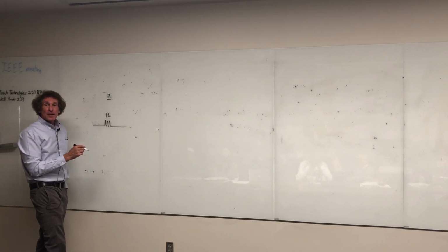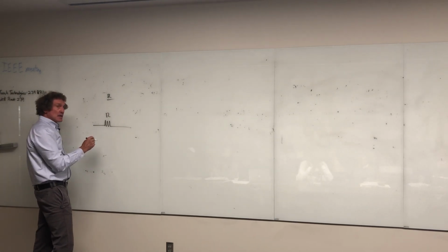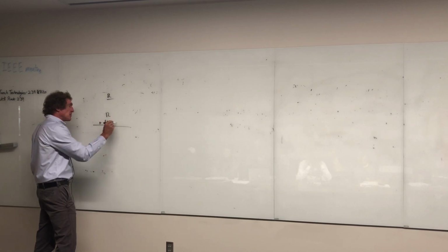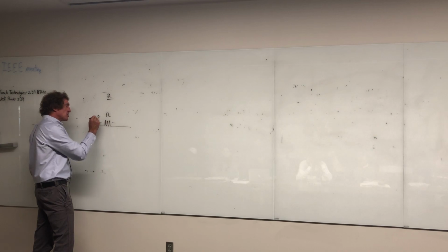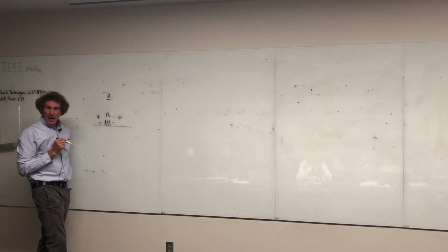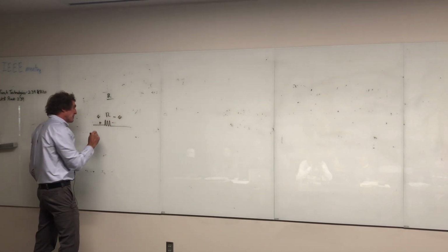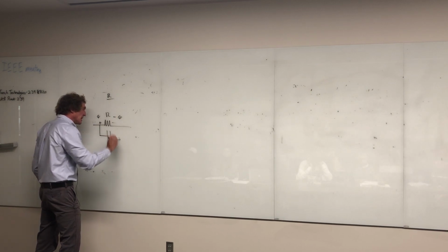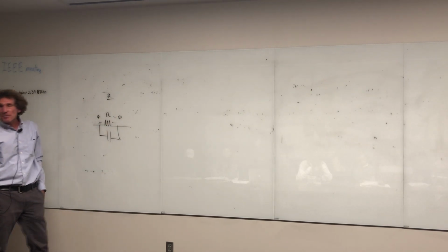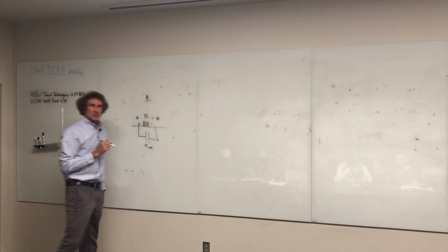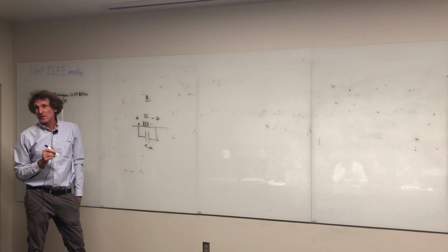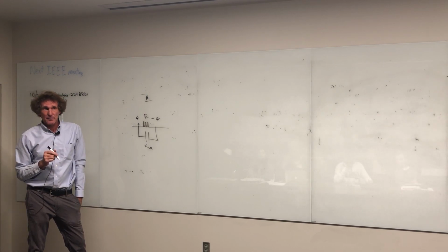In the real world, here's what happens. Because on a resistor, you develop a voltage difference with current flow. You also develop a charge difference, all right? That means there's a real effective capacitance. You can't get around this. There's some capacitance associated with that. You can call it CX the way he does. The X means unwanted. You would like to get rid of it, but you can't.